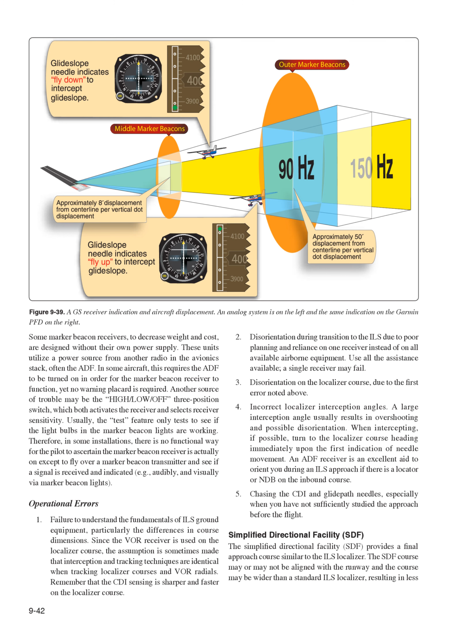Simplified Directional Facility, SDF. The Simplified Directional Facility, SDF, provides a final approach course similar to the ILS localizer.